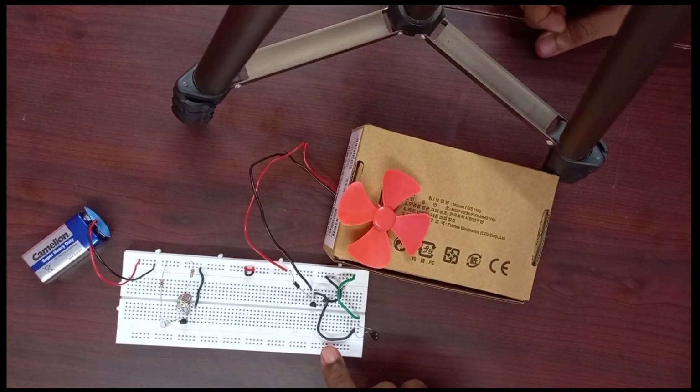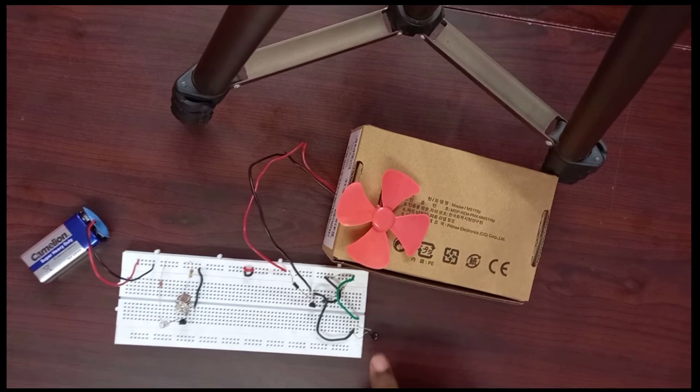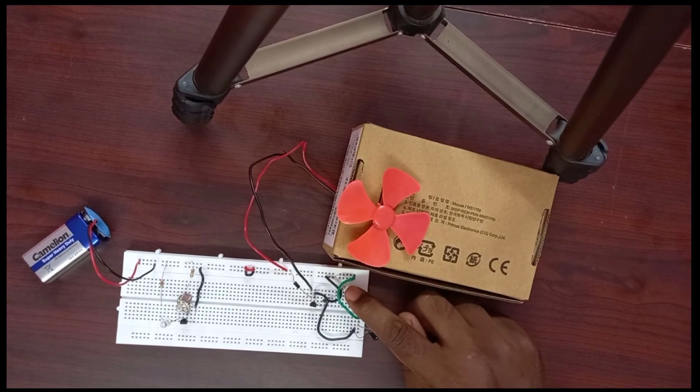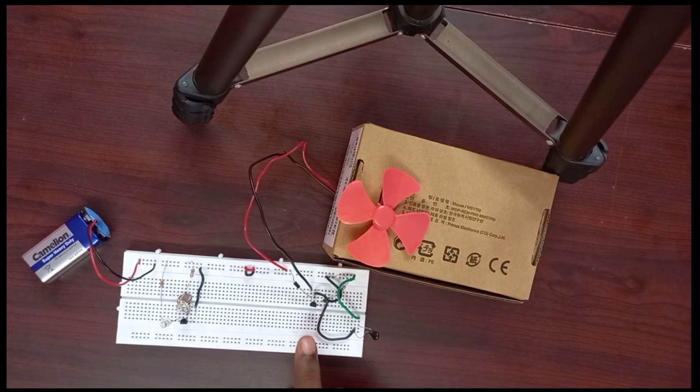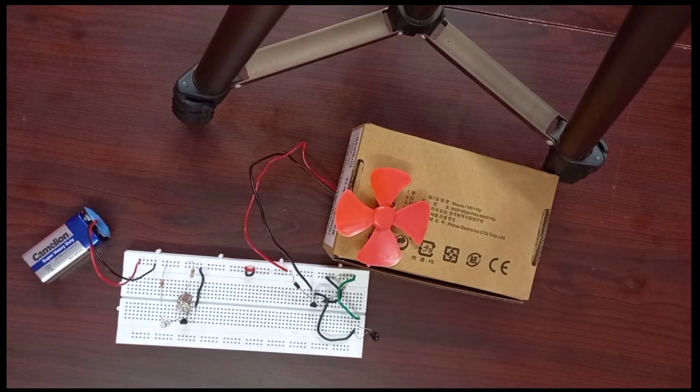Here we have designed a simple circuit for the thermistor. This is the thermistor unit, which is 10K. Then we have a resistance unit, here is the resistance R2 value. This is the BC547 transistor, with the flat surface facing front, with collector, base, and emitter. This is the diode, and across the diode we have connected the motor, like this fan device. To check this condition, we are using a lighter to raise the temperature.